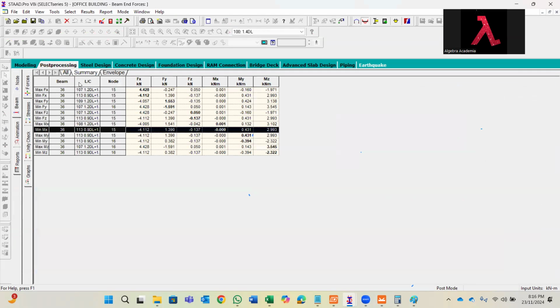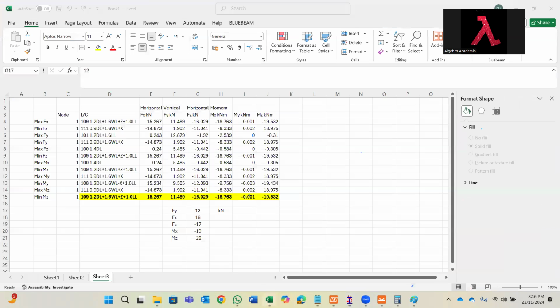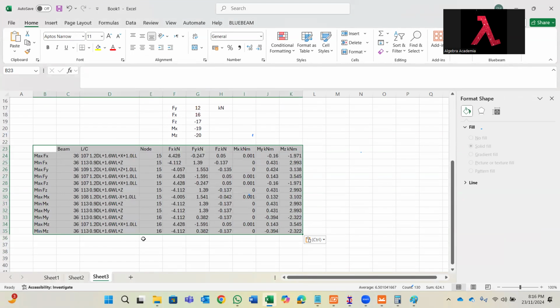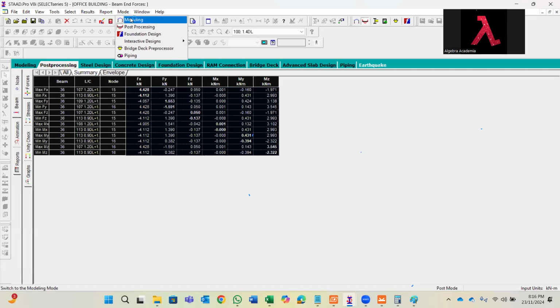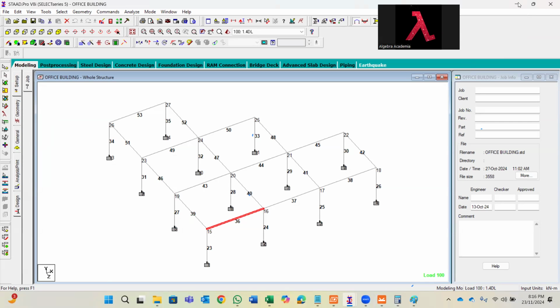Summary here. Okay, so I'll just copy and paste it right here. Then, going back to the STAAD model, the axial force for the beam is Fx, correct? This is axial, which is defined as either tension or compression. I could have horizontal shear in the Fz direction, vertical shear, which is Fy. And obviously I also have indirect tension due to the moment.